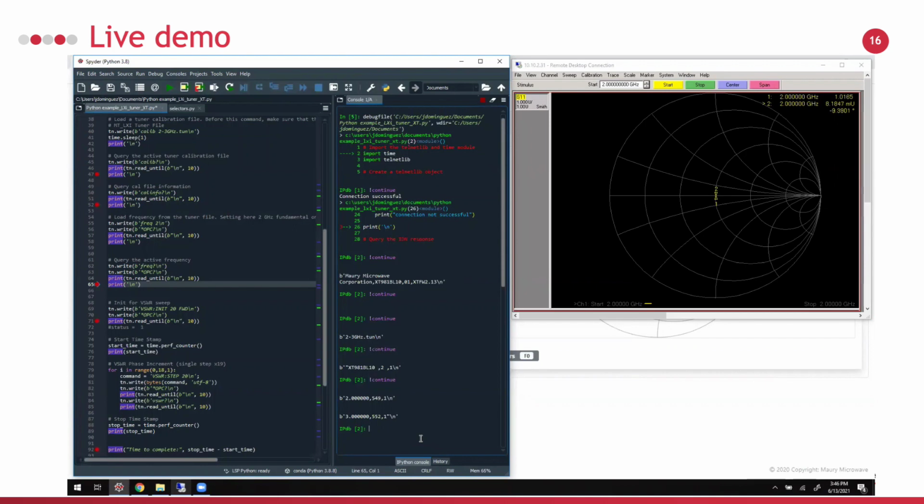using the third approach. Here, we will be setting a VSWR of 20 to 1 and then step 20 degrees at a time to complete the 360-degree rotation. This approach allows a user to take data with other instruments for each VSWR. Here, I'll first be initializing my VSWR with the VSWR init command and then selecting the magnitude that I want to set it to.